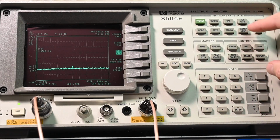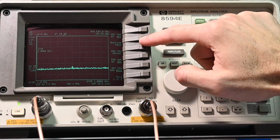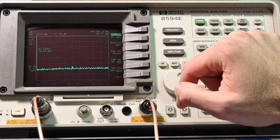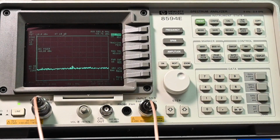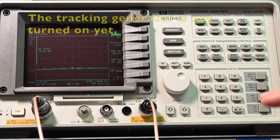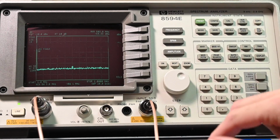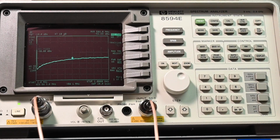And then let's go over here and set up the tracking generator. So go to auxiliary. We're going to go to tracking generator. And it looks like the output power right now is at minus 40 dBm. Maybe a little bit low. Let's just go maybe negative 30. It's probably okay. We don't want to go too excessively high. We don't want to risk damage in any devices that we're testing. But let's try, let's say minus 30 dBm, like so. And that actually turned it on when I entered that value.